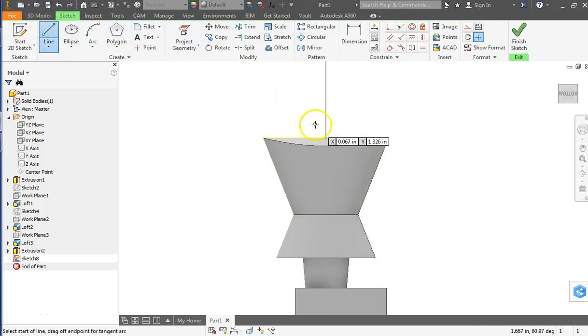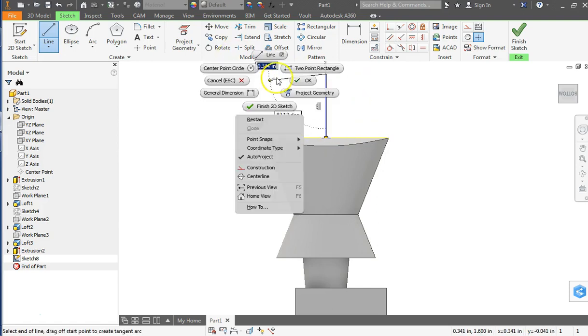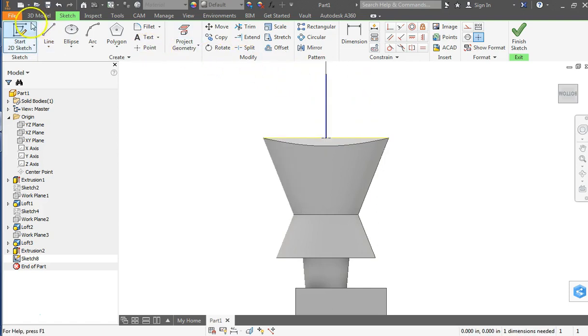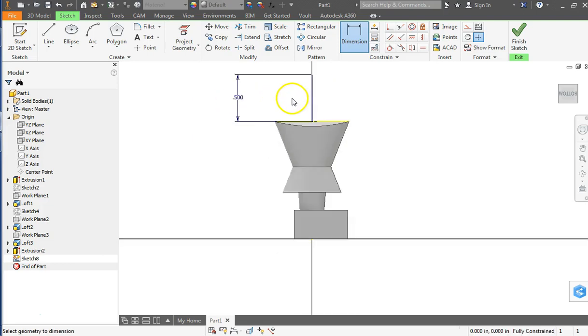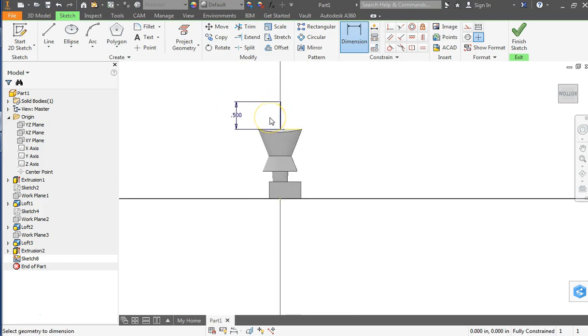I'm going to make a line that goes vertical. My strategy now is to make half of the head, and then I'm going to revolve it. All right, and I'm going to go ahead and dimension the height of this because I did measure the height of the head, and I wrote it down to be about 1/2 inch. It is maybe bigger than you would think. So you might say, wow, it looks proportional, but if you pick up the plastic piece, it's a pretty good size.